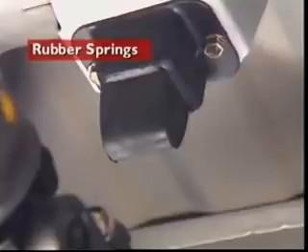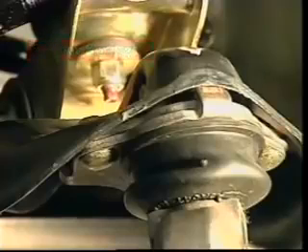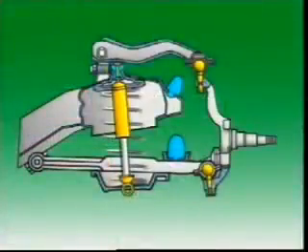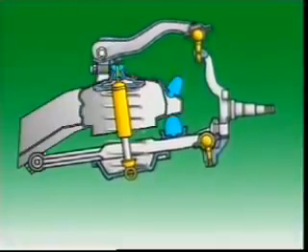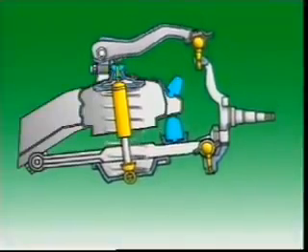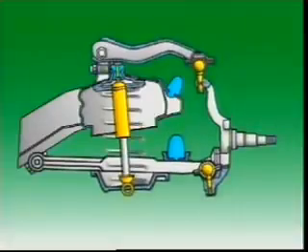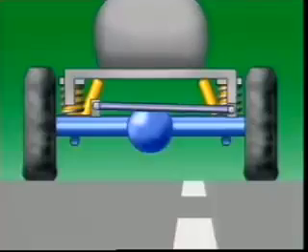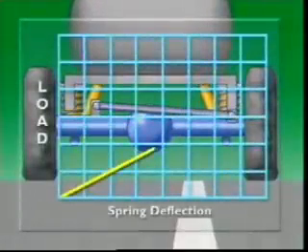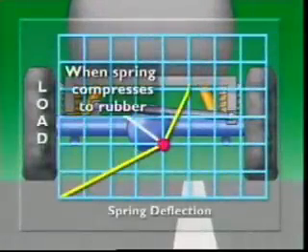This section examines rubber springs. Rubber is used in most suspension systems as bump and rebound stops. If the suspension reaches its limit of travel, these stops prevent direct metal-to-metal contact, which reduces jarring of the body of the vehicle.